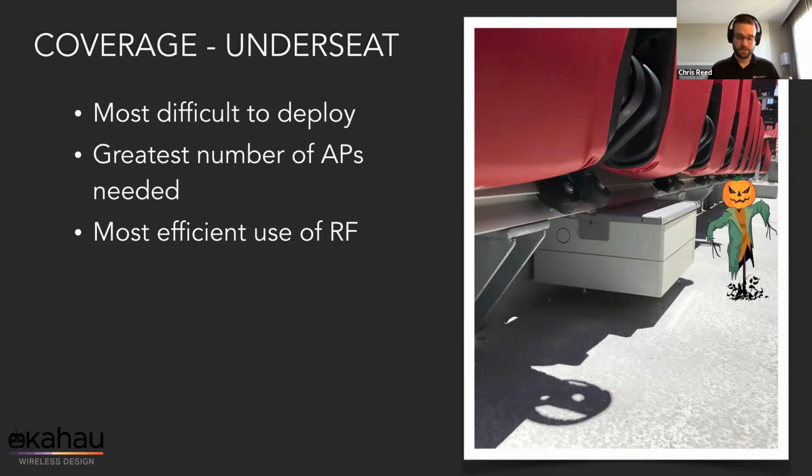You've got to do a lot as far as enclosures and aesthetics to make sure that they fit with the venue aesthetics, because they're right in the face of the clients. And then there are things like having to core through concrete, or if it's a slab on grade, or the seating is all just on grade, you can't core through. There's nothing underneath it. So you've got to figure out some sort of tracking solution, and there's nothing off the shelf that you can use in a permanent install. So it's often all custom, unless there's an off-the-shelf one that you know of. I haven't been able to find one.